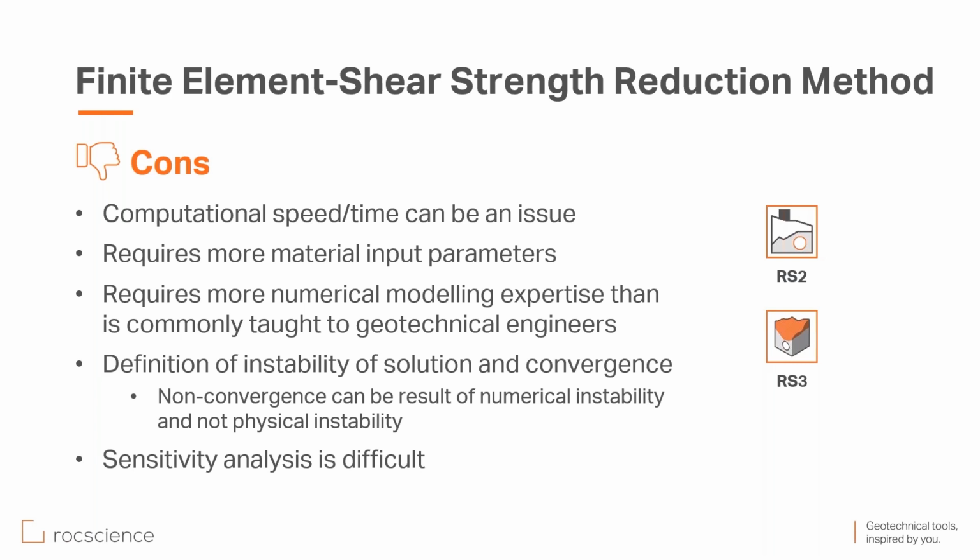Again, because we are running finite element, it's a little more complex, so it requires more numerical modeling expertise than is commonly taught to geotechnical engineers, for example, at undergrad levels. One of the things that is a subject of discussion is the definition of instability of the solution. What we use in RS2 and RS3 is non-convergence as the definition of failure.